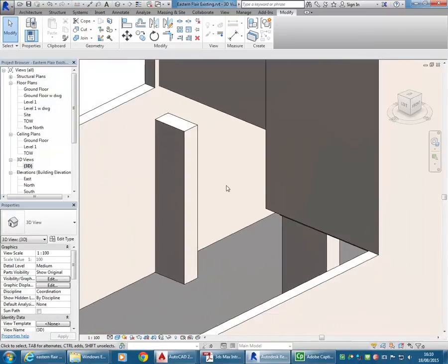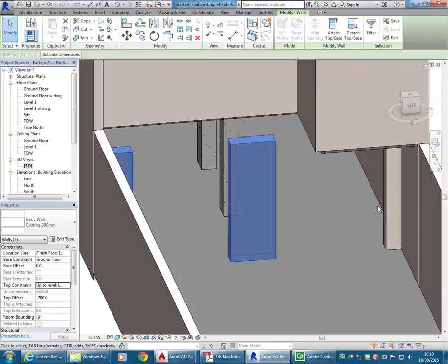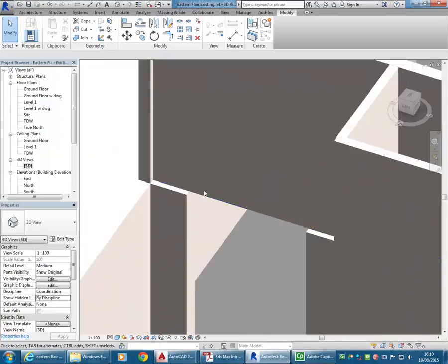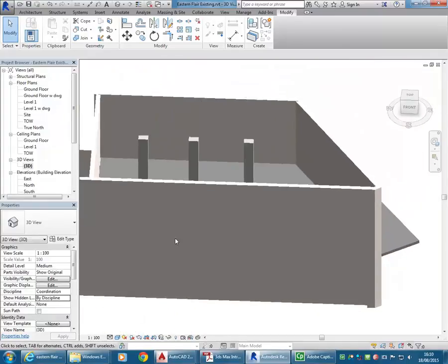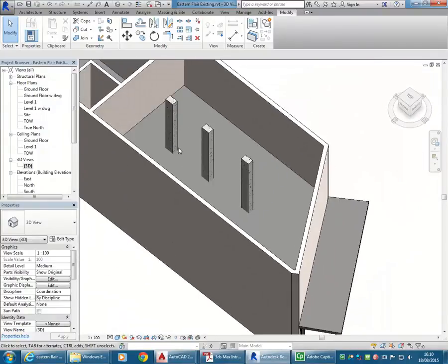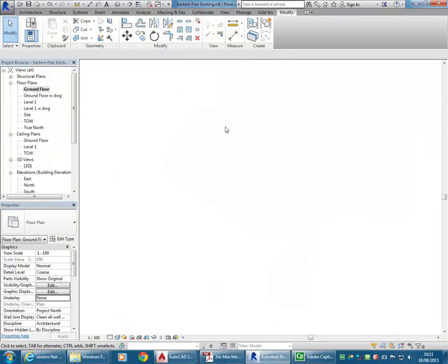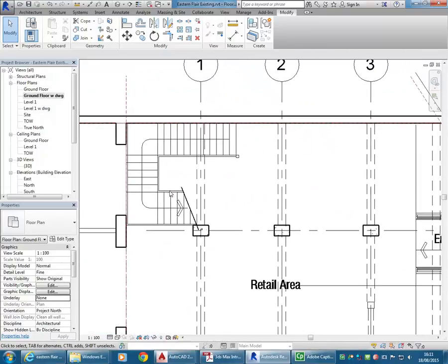So then finally these walls here need to be extended. By selecting each one, I can change, there we go, the top offset was still set to 700, so I'll take it back to 0. So that's right now, and they connect to the wall above, which is how they should be. So then the beams above should really be put in, but might leave that for now and just move on to the stairs. Because that will give you a good indication of the void area that's above these stairs.